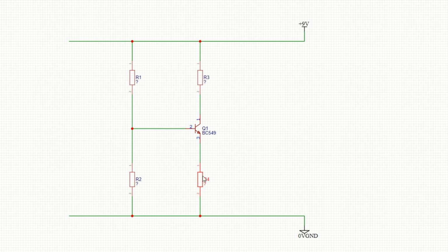Right, okay. So the principles are: the current is set by those 2 resistors, or the maximum possible current is set by those 2 resistors if the transistor turns fully on. And of course, if the transistor turns fully off, there's no current through those 2. If the transistor turns on part way, so that the collector voltage is somewhere around half to 2/3 supply,